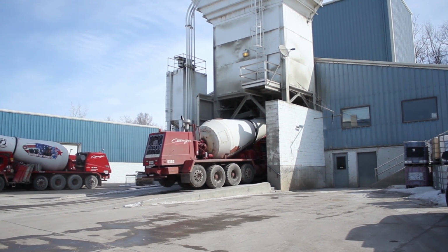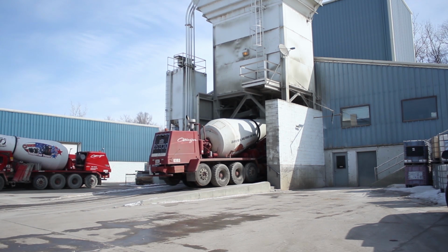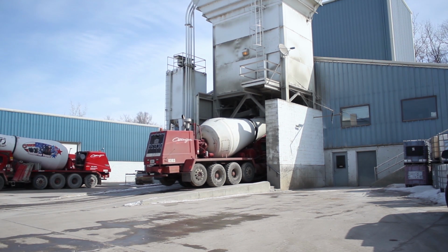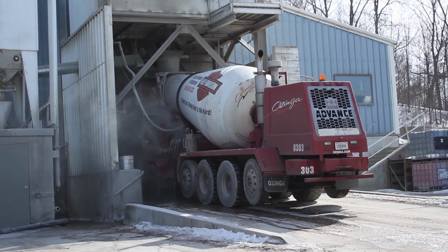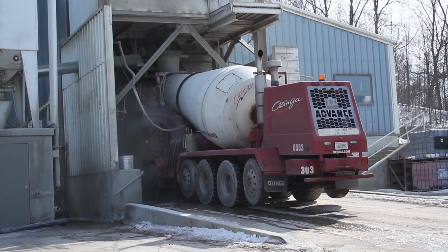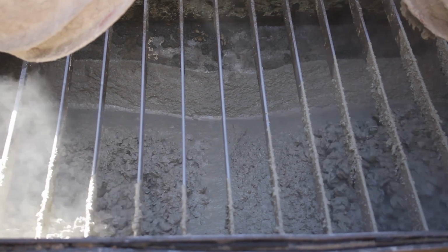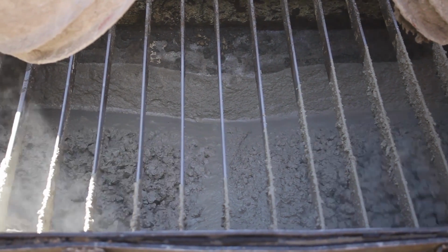Some mixes contain chemicals that make them more workable while using less water, and this can throw the slump readings off. For example, mixes with no air entrainment tend to read stiffer than they actually are. Also, the size of the load can affect the slump meter, with small loads reading a greater slump than large loads. Because of these things, the slump meter is a good indication of slump, but the only way to be totally sure your slump is right is to visually inspect the concrete to see that it is the right consistency.